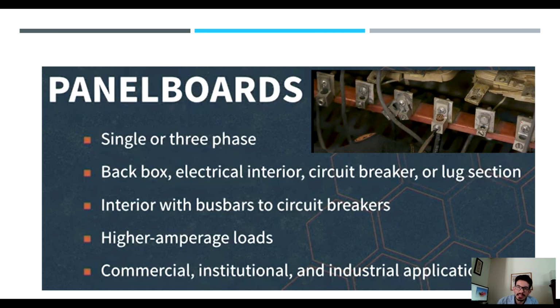So it is very important to have access to the whole control box and be able to switch the power on and off depending on the type of maintenance that you're providing. If you're doing maintenance on the box, the switch obviously has to be off. The control panel has to be without any voltage or current going through it. Then you can change the wires and connectors and terminals, etc. So it is very important that you have access to a control box for maintenance that has no power.